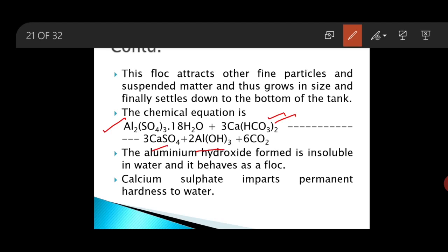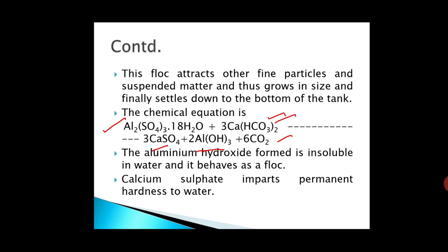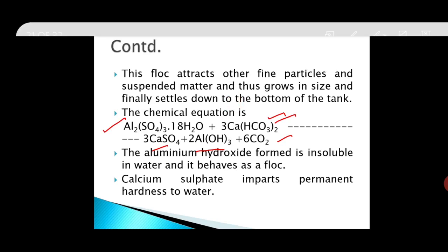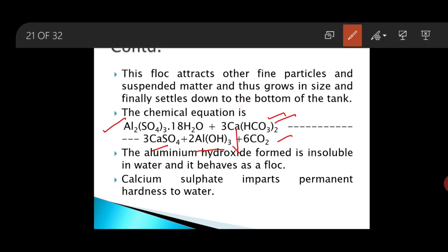This aluminium hydroxide is the floc, and it will also liberate carbon dioxide, which will cause corrosion, and this calcium sulfate will impart permanent hardness to water. Clear? This aluminium hydroxide floc will attract other colloidal particles and settle down at the bottom of the tank.